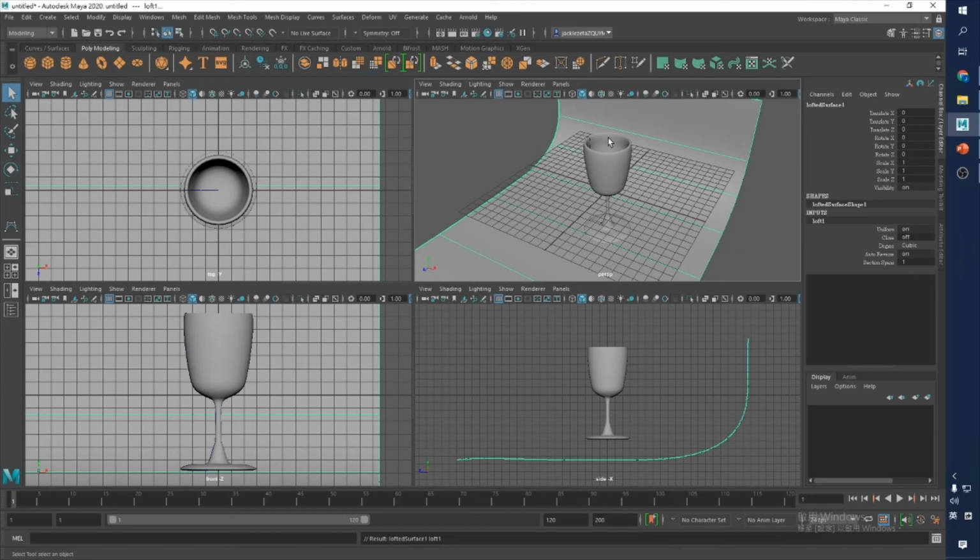Why do we duplicate the curve to generate this surface? Because both curves will have the same number of vertices and the same structure. Certainly, we can use different curves to generate the surface with the Loft command. But if you use two different curves whose numbers of vertices have a large difference, then the result might not be good. So if we are using two different curves, the number of vertices and the structure of the curves should be similar. Then the result will be better.